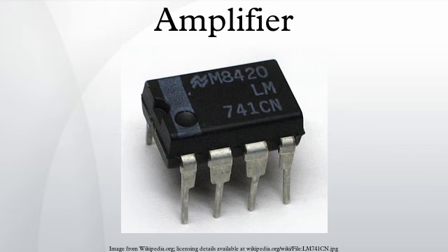Significant efficiency gains can be achieved but with the drawback of more complicated supply design and reduced THD performance. In common designs, a voltage drop of about 10 V is maintained over the output transistors in Class H circuits. The picture above shows positive supply voltage of the output stage and the voltage at the speaker output. The boost of the supply voltage is shown for a real music signal.